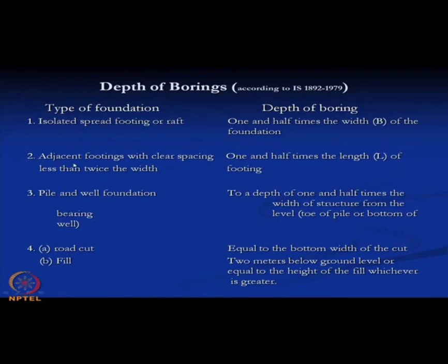Now, if adjacent footing with clear spacing less than twice the width, then also 1.5 times the length of the footing. Then if it is a pile and well foundation, then to a depth of 1.5 times the width of the structure from the toe of the pile or the bottom of the well.